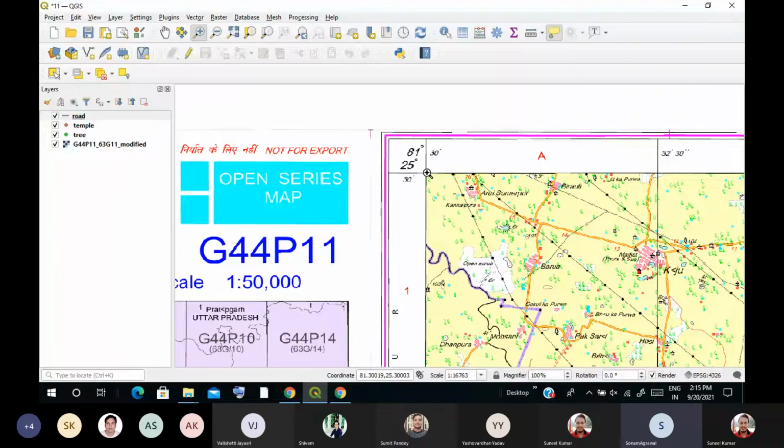आपका आना चाहिए 81.5 और 25.5। डीडी और डीएमएस दोनों लास्ट लेक्चर में आपको पूरा क्लियरली समझाया गया है। आपने डीएमएस नोटेशन दे दिया, उसको डीडी में कन्वर्ट करना चाहिए था। 81 डिग्री 30 मिनट डेसिमल में 81.5 आ रही है, सो इट शुड बी 81.5 एंड 25.5।